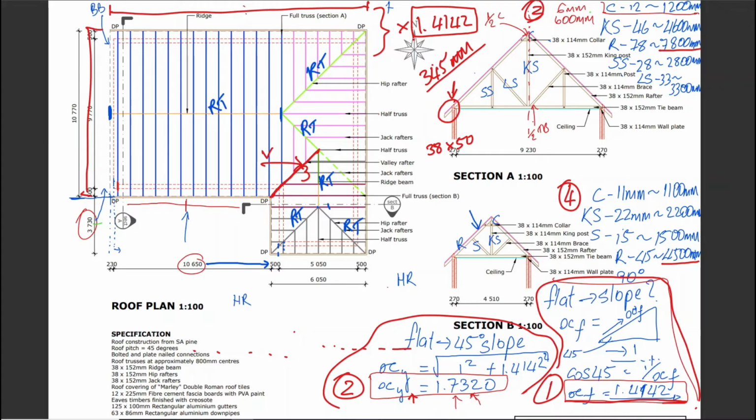So I would say if you want to be really creative, do that spacing division thing, but take a known value. Let's say you could use this full rafter. You're going to take the divisions again, and then multiply it by how many divisions there are on this side, and that's a foolproof way of calculating these things.